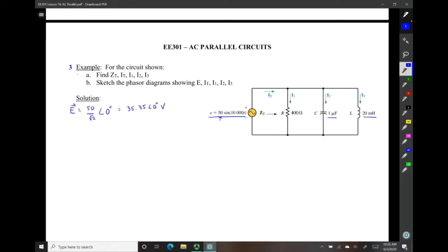Okay, now we solve for the impedance of our capacitor, which if we pull from our equation sheet is just 1 over omega times C. And then we also have to tag on this minus 90 degrees. And that's equivalent to adding a negative j to that value.